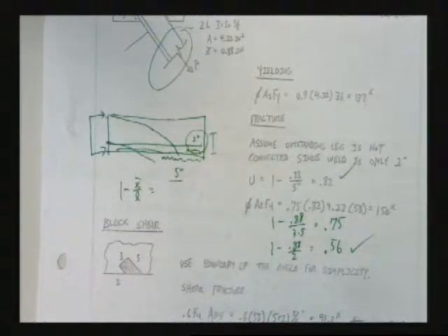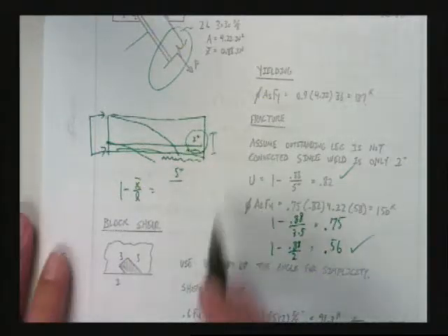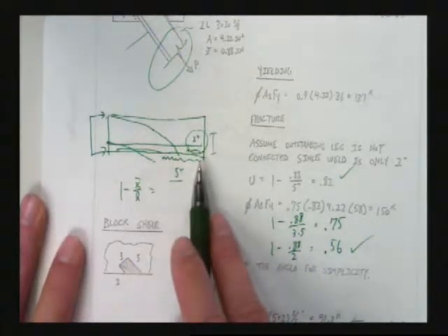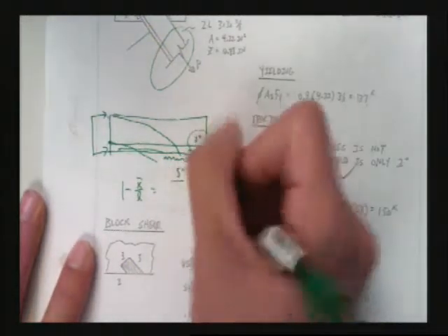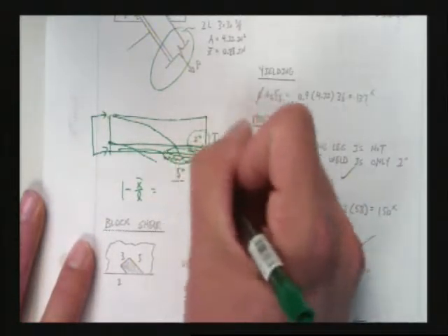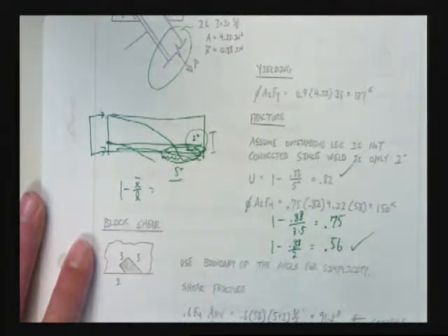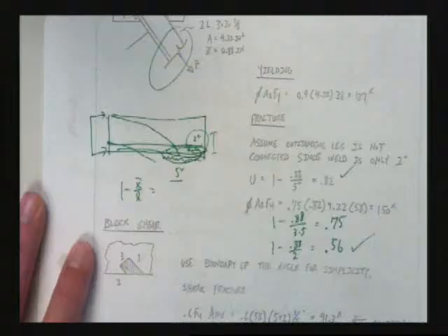Now, just to ultimately bound the problem, what is one way I could work this problem and not have to even worry about any of these assumptions? Well, I could actually assume my load is only transferred by my bottom plate. You with me? That's pretty conservative, isn't it? And I can already see the deer in the headlights look that engineers get when they start to have to use engineering judgments. Which one do I pick? Which one is right? Guess what? That's what this class is inadvertently all about. Big emphasis.